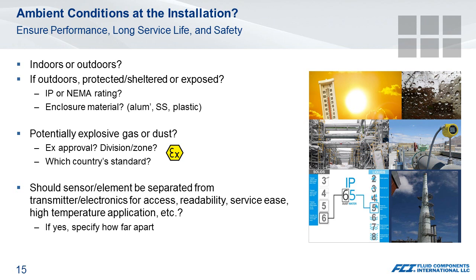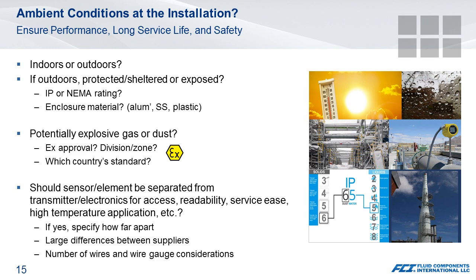Some manufacturers may do only 50 feet, while others will do 1,000 feet. It also will affect the product selection and the distance, the number of wires used, and the wire gauge considerations. So if it's going to be remote, be sure you're putting in your specifications the distance that's required.